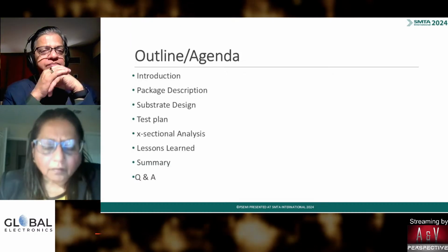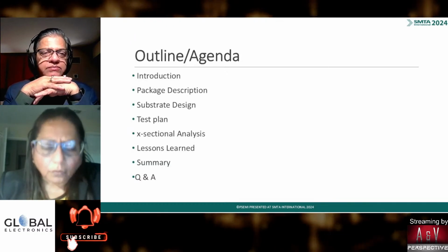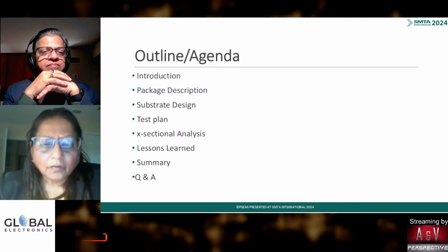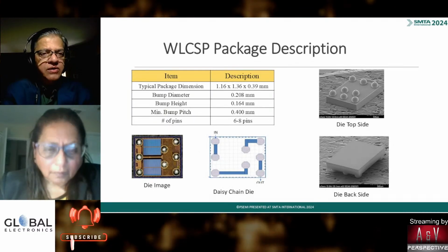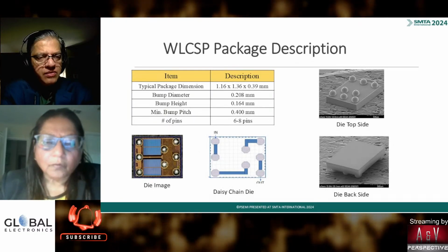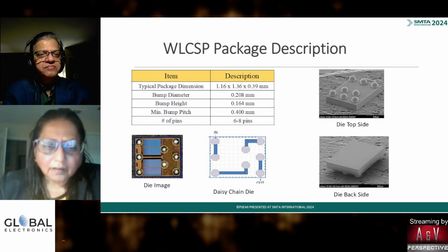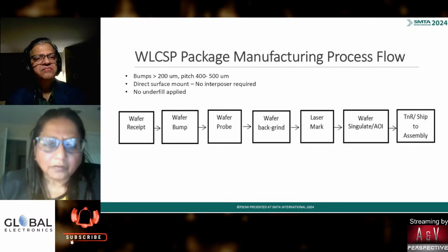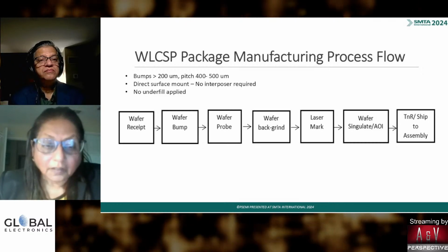But we as component manufacturers are also looking on our own to conduct board level reliability testing, so we can have a better feel for how the component survives in the field. Typical tests for components are thermal cycling, thermal shock, temperature humidity, and high temperature storage. But we have not been doing too many of the mechanical tests.